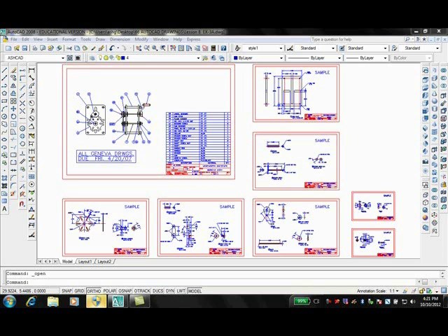When a drawing has to be plotted at 1/2 scale, it would require a DIMSCALE of 2, whereas a drawing to be plotted at full scale, 1:1, only requires a DIMSCALE of 1, which is the default. However, plotting at 1/4 scale would require a DIMSCALE of 4, and so on.